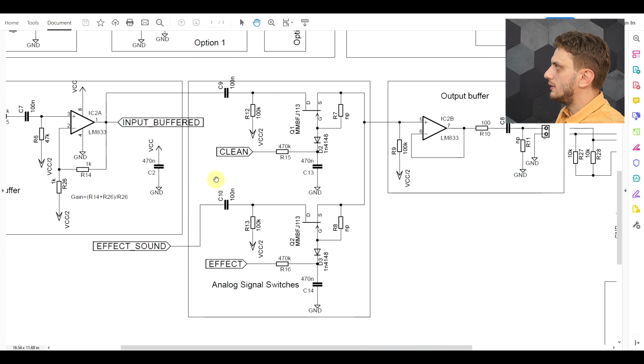And secondly, I wanted to handle the popping sound that occurred when you went from the affected channel to the clean channel, and vice versa. So even with no signal applied, you still had a popping sound when you went between these two channels. And for this, the first modification that I brought was the driving signal to the transistors. So this RC circuit had its values increased tenfold, both the resistor and the capacitor. This brings a much slower signal into the gate of the transistor. I also removed this source gate resistor. The transistor was switching just fine without it. And finally, I reduced the values of these stabilizing resistors, so R12, 13 and 9.